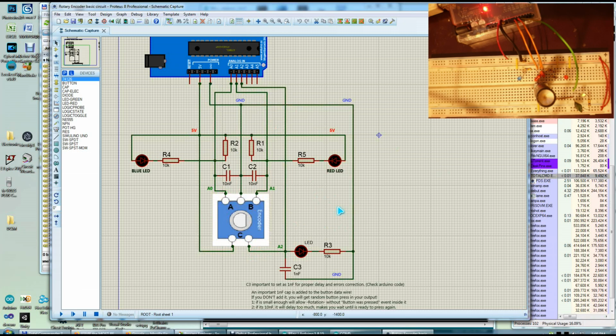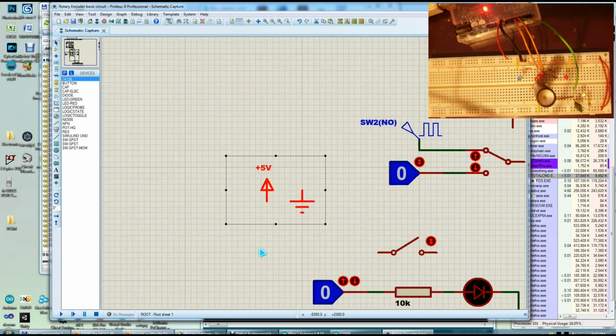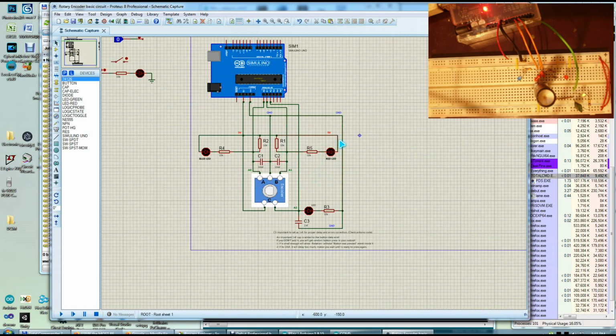Why I wired it like this is because I'm building this stuff. So it's very beneficial for me to have it in this a bit more complicated way of showing the schematic, to actually see the wiring when I'm wiring the circuit, because like you know me already, I'm actually soldering the wire tracks, all these wire tracks. So that's why my circuit diagram is not using these positive and negative symbols. I could have used them very easily, especially for LEDs, here the positive, and here on this lower part, that negative, that ground symbol. But I wanted specifically to link with wires because I'm building all this circuit later.